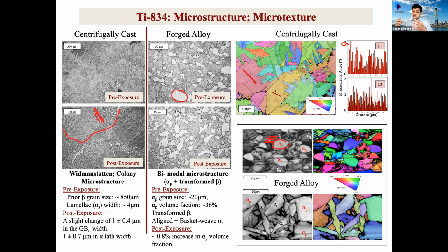That's what restricts the dislocation from going through, so the crack formation or slip transmission is restricted, and it also makes an obstacle for them to pass through the neighboring grain, and that makes the material much stronger.